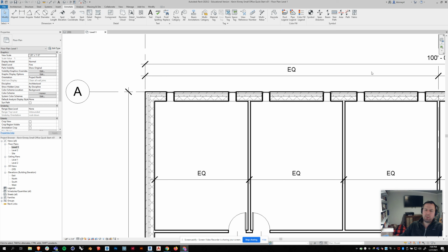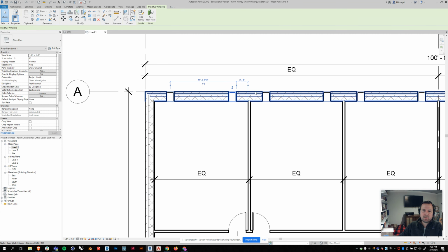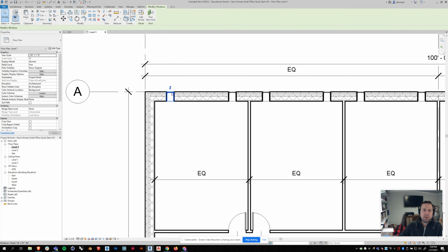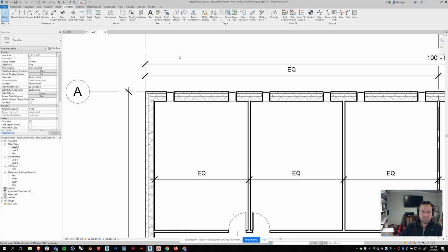I am back. I was just looking up a solve for something. So sometimes when you click on an element and you adjusted the dimensions just like I did when I had the wall over on the left-hand side, it's really annoying, but now when I click on the window, the dimensions aren't there anymore. So how do I get them back? Because if I click on this window, hey, I got my temporary dimensions there. How come I can't see them anymore in this one? Is it because I edited them with that other wall? I'm not sure, but let me just show you a trick to make this editable with dimensions again.